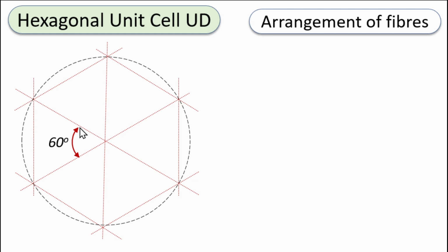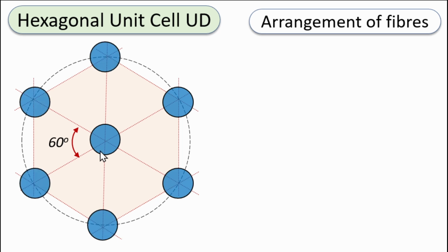If we then think about the angles inside this regular hexagon, they will be 60 degrees. What we then need to do is to circumscribe the circles as shown here. These are the circles taking positions along the edges or the points of intersection of this hexagon. There is a distance we can note here. The diameter of these fibers is df, and there is a distance which is basically the radius of the circumscribed circle. This radius is equal to the edge length of the hexagon, because in the end this is going to be an equilateral triangle, so this distance is s.